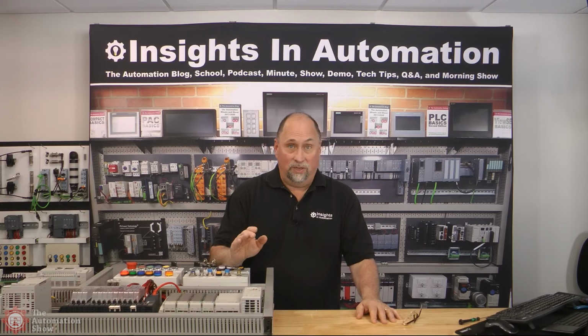I love that it calculated the power for me too, because you can only have so much power per bank of I/O, right? So you need a new power supply every so often based on how many I/Os you're going to have, for both bus and field power. And so that's something you have to consider. And I just thought it was very intuitive, except for those couple little things I showed you that I ran into, first time using it.